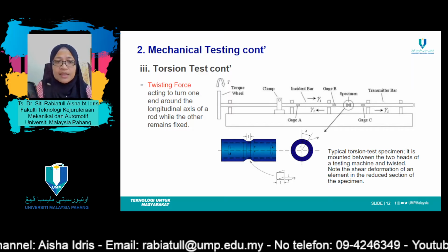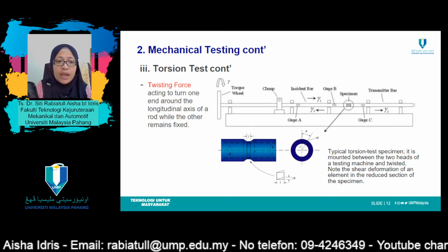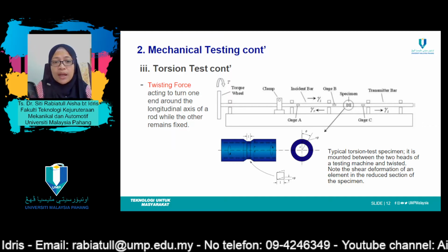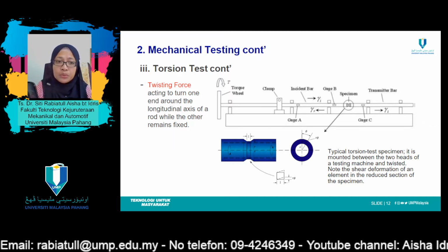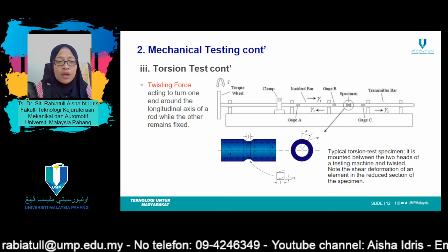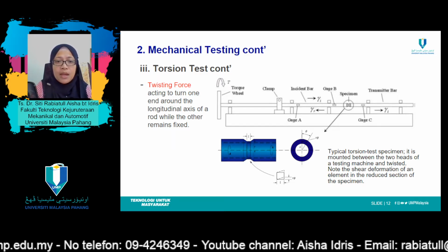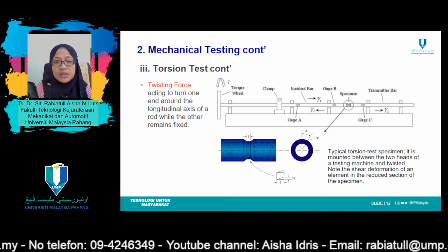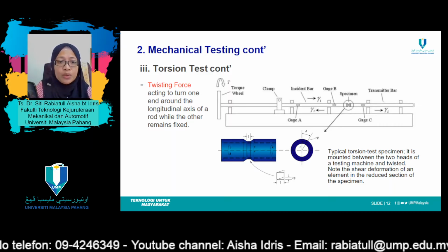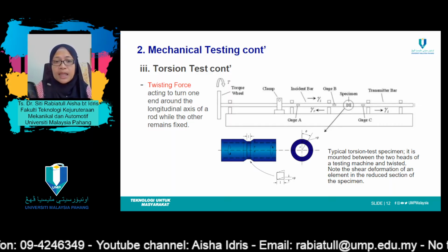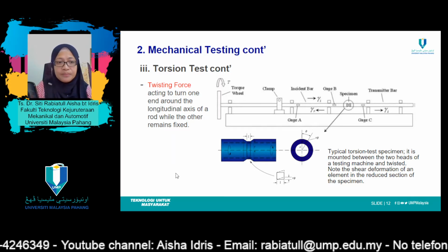Torsion testing is appropriate for materials that may experience a torsional load, like a metallic bone screw and intramedullary rod, rubber tubing that may become twisted, or to measure the shear strength of a bond between an implant and native tissues like bone.